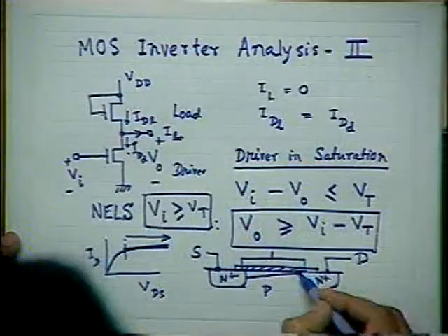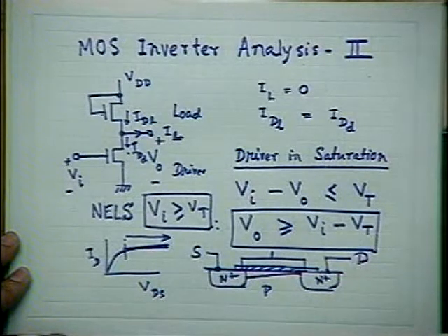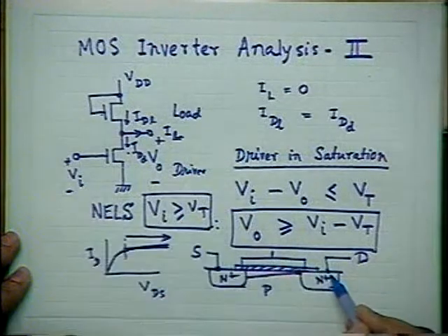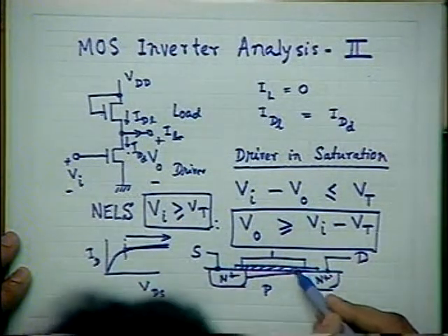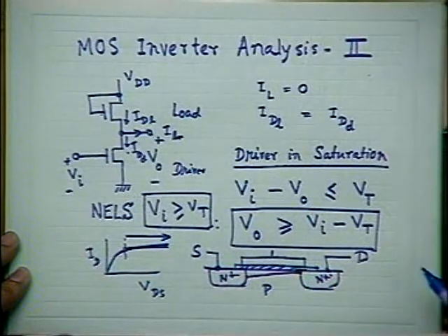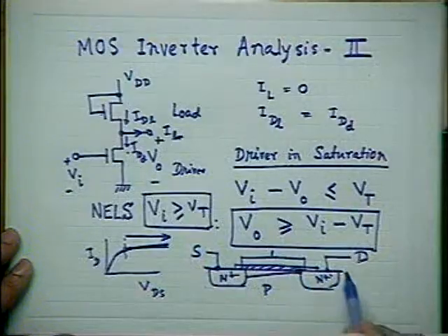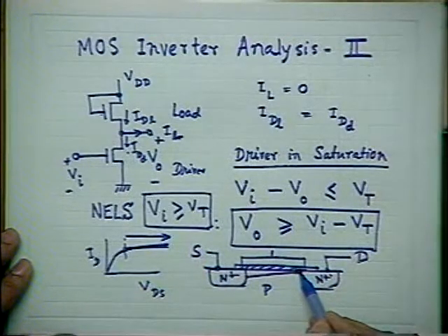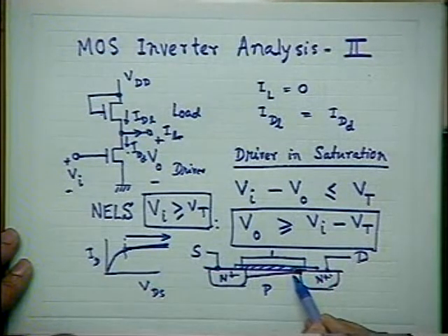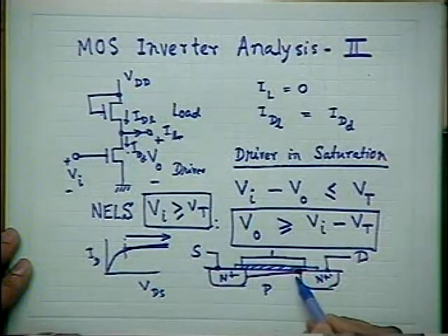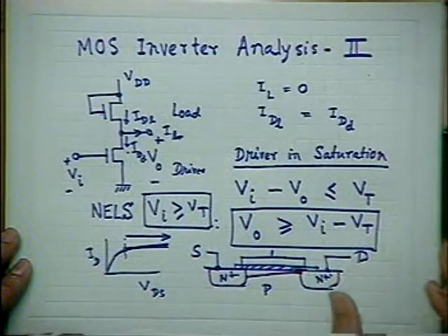That means in the drain side, no inversion layer is formed. And that is ensured by the fact that VGS minus VDS is less than VT. So naturally at this end, there will be no inversion layer formed. And I think I've told you that under this condition, the entire drain voltage appears across this very small region. As a result, there is a very strong electric field inside, which results in a condition called the saturation velocity. The carriers drift with saturation velocity under this very strong field, and as a result, the current gets saturated. That was the reason.